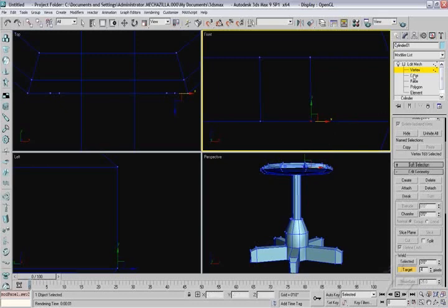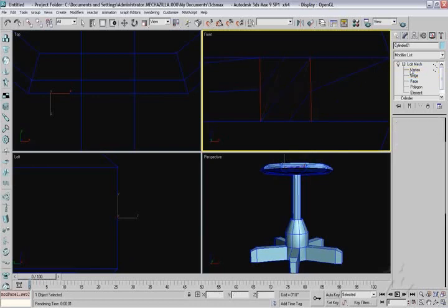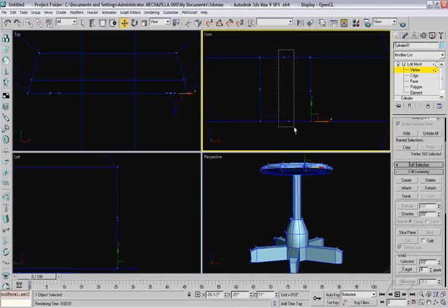Okay, while I'm down here nice and close up, I'm going to click on edge mode and use my divide tool and divide that edge, this edge, that one, and that one. And then back in vertex mode, I can select those new vertices I just created and scale them out to make more of an octagonal type shape. Using my 2D scale in the front viewport, I'm just pushing those forward just to make a nice rounded kind of polygon to extrude from.